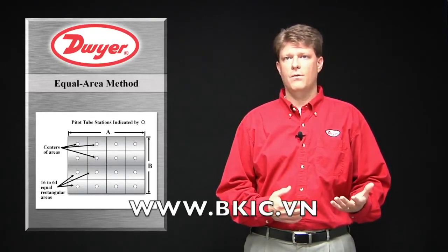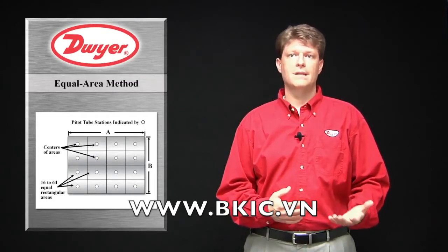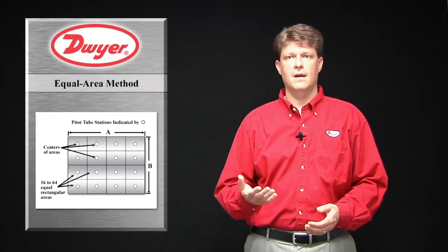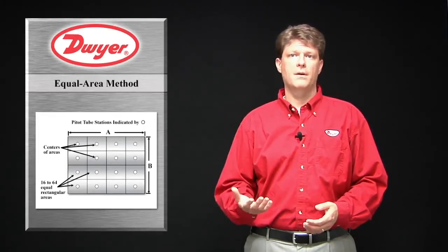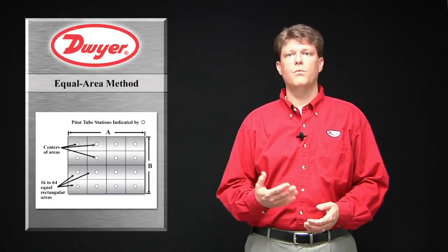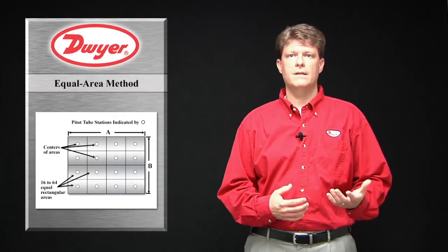If less than 64 reading points are being taken, the distance between the points should not be more than 6 inches. In the example shown, 4 holes are drilled into the duct and the pitot tube or anemometer is inserted into each hole to take 4 readings traversing the duct width or height. The reading points are the center of each of the rectangles as shown.